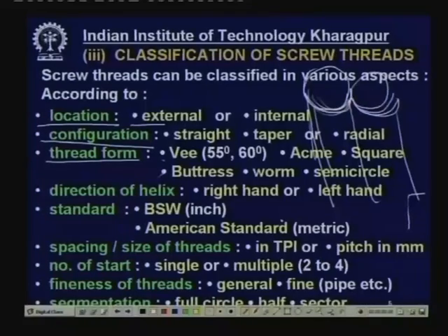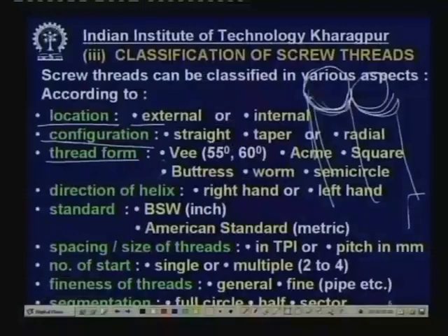You know, in all screw nut systems, the threads are subjected to sliding. Okay, a lot of friction, rise in temperature, wear and tear take place. But there are modern screws where the contact is through rolling. A set of balls roll in between the threads of the nut and screw. In that case, the grooves of the threads of the nut and bolt both are made semicircular.